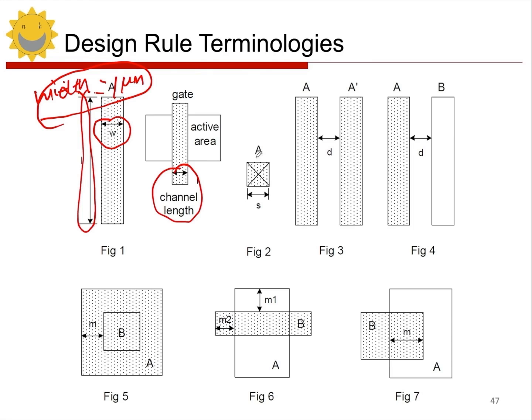Next, we have size, right? It's been mentioned that it must be a square, and it represents the length of the sides of the square, which is fixed. This is different from other parameters, which usually have a range. For example, the Y's parameter might say it must be less than 1 micrometer, so I could draw 0.8 or 0.9, and both would be acceptable. But size is different. It is equal to 0.2 micrometers, meaning it can only be 0.2. No other values are allowed.